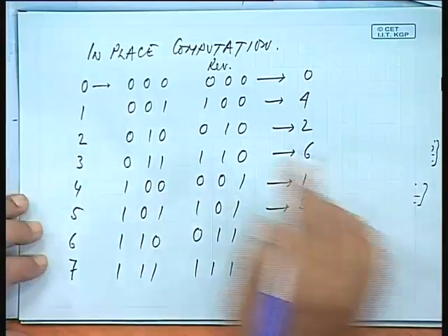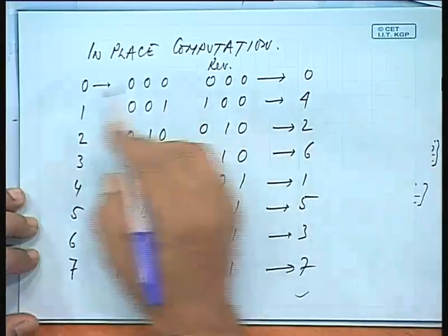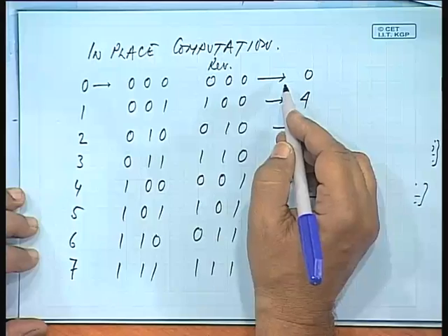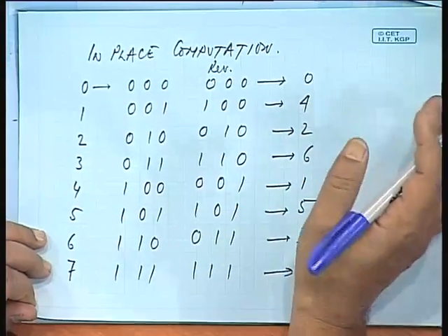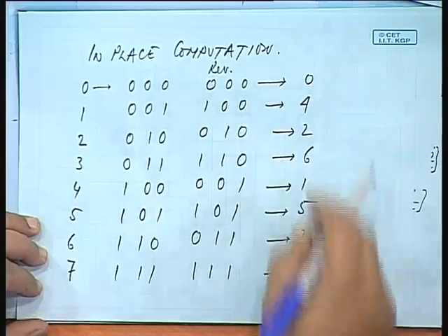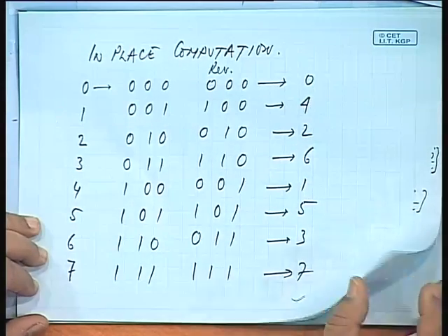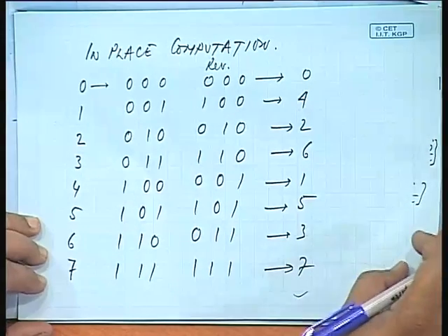So, this is known as the bit reversal technique. You express them in binary digits, then you reverse them and again convert back to decimal numbers, and you get the reversed sequence. So, you shuffle the data in this sequence, you will get this.